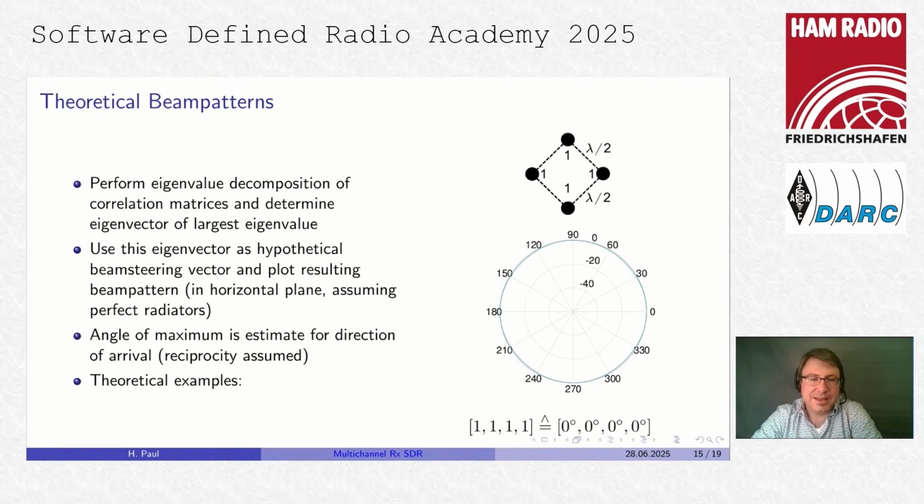And what you basically do is you take a vector and use it as a so-called beam steering vector. Means when you look at this figure, feeding these 4 antennas in the foursquare constellation with the same transmit signal, you get a radiation pattern which looks like this. This is almost a perfect circle.